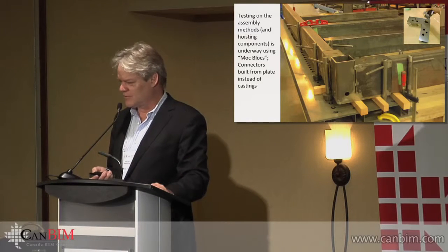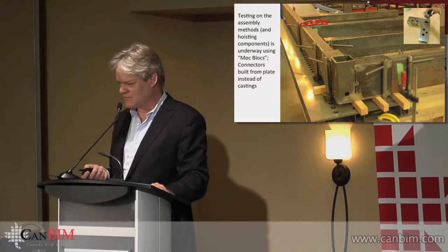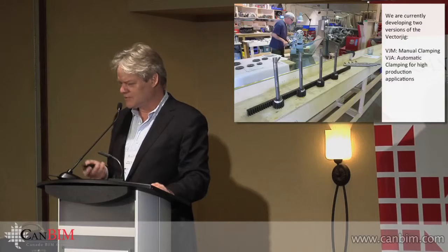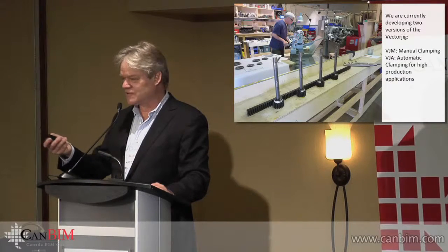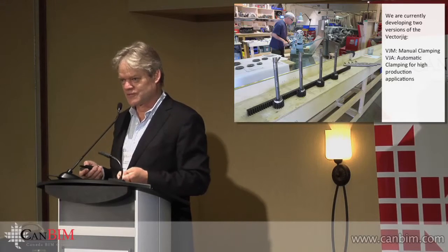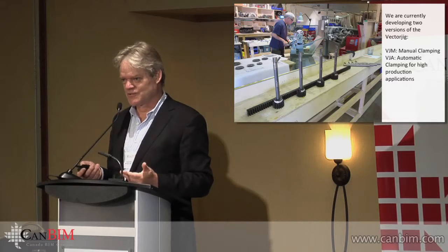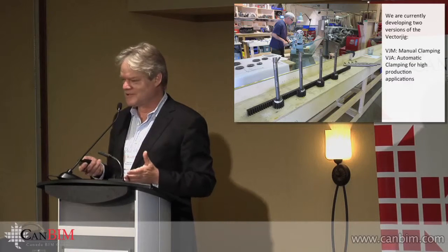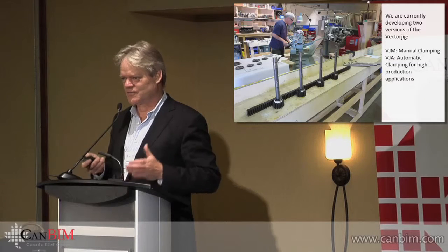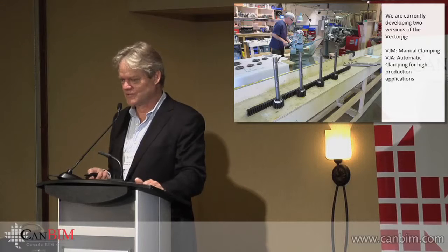There's an image of the prototype that we're working on in the plant. That picture was taken yesterday. You can see the laser cut plate with these pins fitting into it. And this shows a row of the pins activated by a rack, so that the hydraulic ram operating the rack will rotate the pins and perform the clamping action. We're foreseeing a jig where, for somebody who wants to invest the money in it, the rate at which the jig can be loaded, the welding conducted, and the part released will be reduced to minutes.